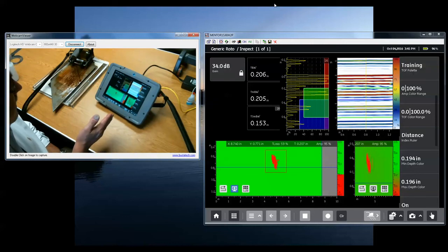Now, any place that the instrument did not take a thickness reading, so the thresholds didn't break the gate, or for whatever reason we didn't take a reading, those areas are going to also be red. The no reading gets translated to 0, which is less than 194, so it's the most red color.